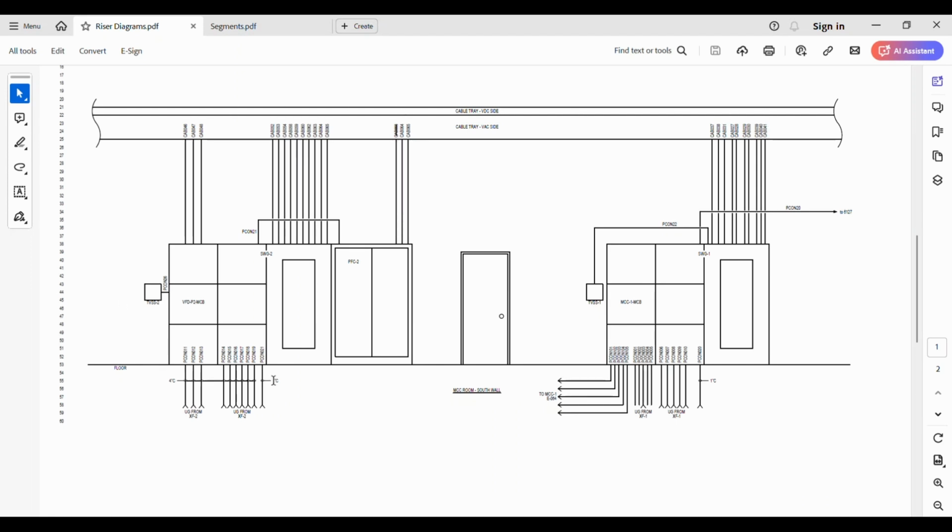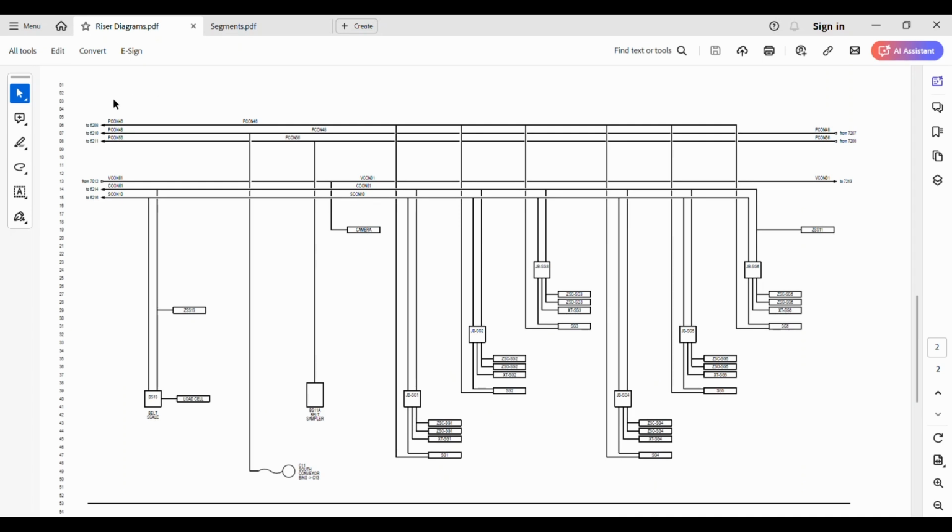This only shows you a little bit of the actual effort to do the CAD portion of it, but you've also got the schedule, so you've got a spreadsheet, you've got calculations on how big each one of these trunk lines is. As cables drop off a trunk line, the conduit gets smaller. All those calculations, you've got multiple cables in a single conduit. Very seldom are they actual single conductors, so there's no code tables to help you sizing that. And I have actually generated over my career several different spreadsheets to do all these particular activities.